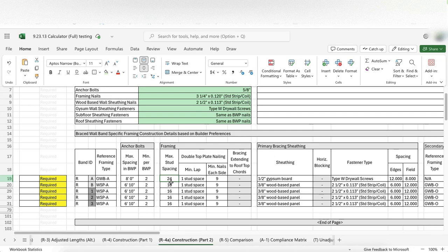This maximum stud spacing might be calling something out here based on the bracing requirements, but there are other Part 9 requirements that could potentially produce an on-center spacing of 12 inches, for example. So I am working on producing some of that logic into here.